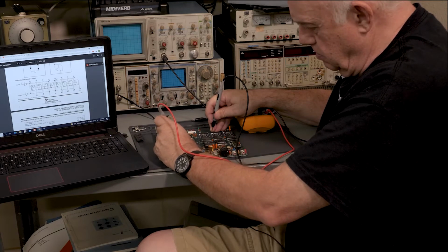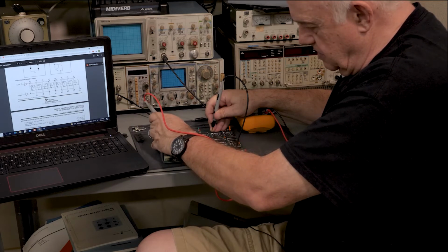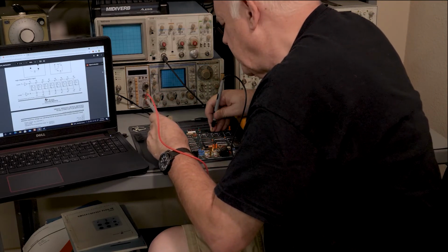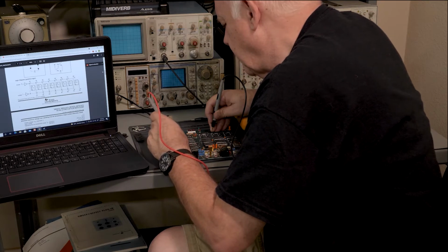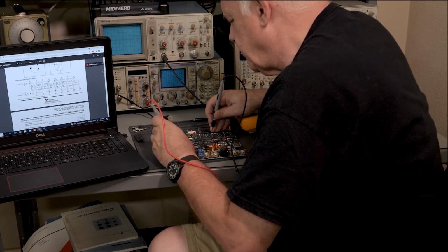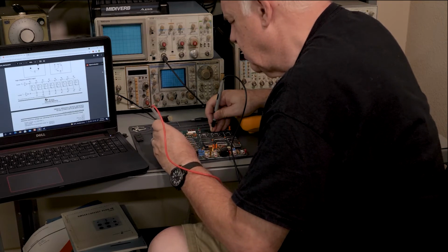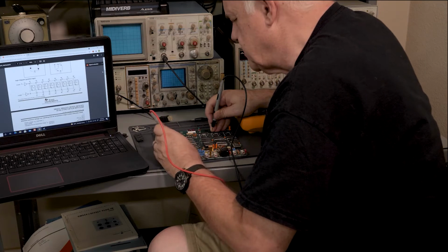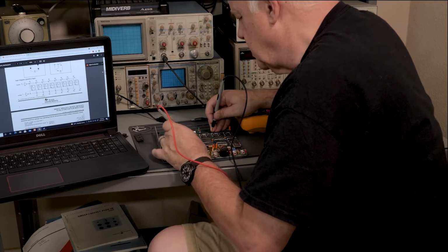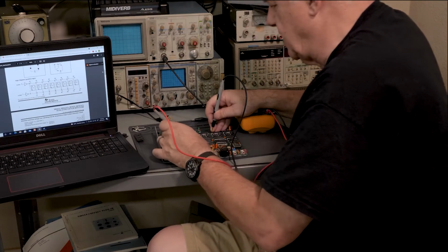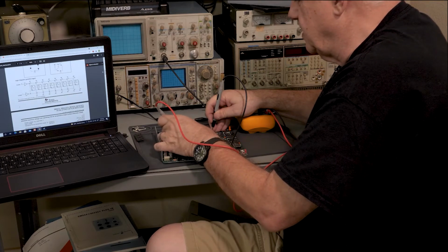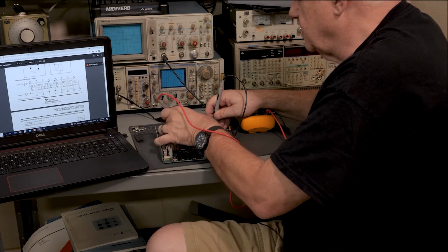Wait a minute. I got the one next to it. Right there. And it turns out that's a flip-flop. That's on pin 6 of a flip-flop. Is it anywhere else? Okay. Without knowing what pin 6 is, it could be an input, could be an output. The answer is no. If I sit here and scrape across all these chips doing what I call a sweep, that's the only place it goes that I know of.